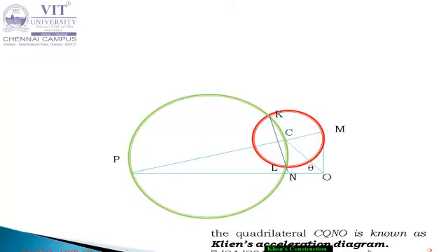After that, you have to name the intersection point. It cuts the connecting rod, or the line along the connecting rod, at Q. So now you have a polygon, okay, CQNO. This CQNO gives the acceleration diagram. If you draw a separate acceleration diagram, that reflects the same shape.